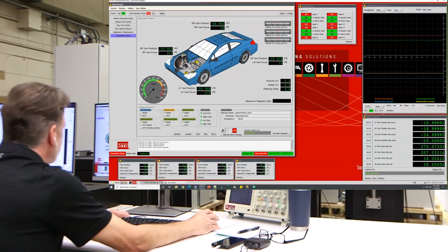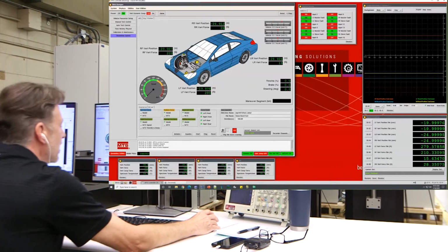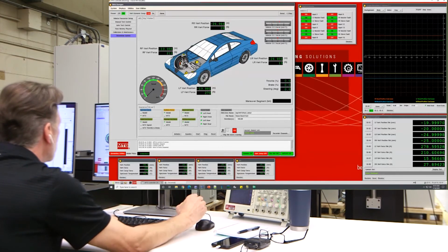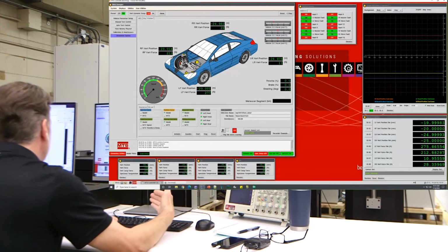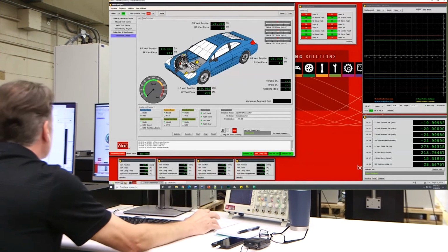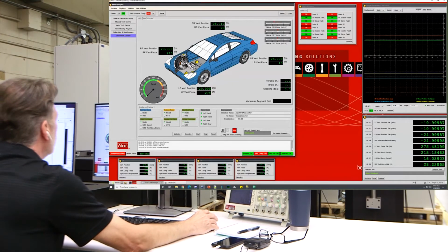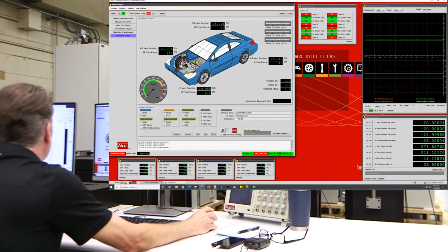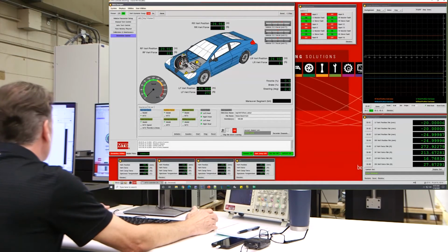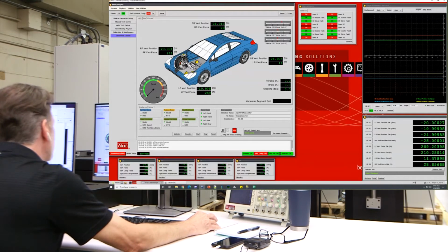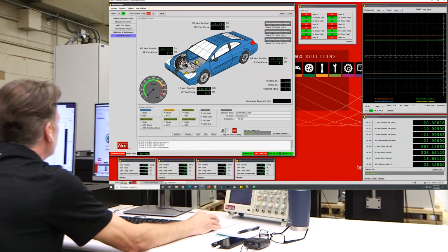As I said, we're going to be demonstrating that in a ride event. We can take over steering input if we have a time history of the driver on the proving ground and we want to play exactly that out. You obviously can put that into the simulation, but we can drive it externally here. To go through a number of maneuvers, sometimes we want to, for example, change the vehicle speed. We've got the ability to do that, and we can run a maneuver at 40, 60, 80 kph, much as you do out on the proving ground. Once we have made the switches for command and feedback, then we're going to start the simulation.